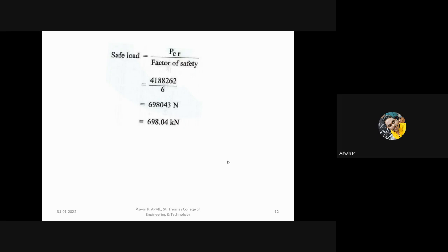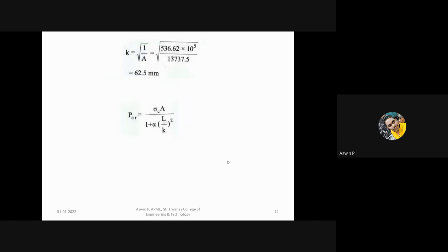So this is the method of solving a problem. We will once again check the problem and how we have done it. The given problem is a hollow cylindrical cast iron column, 200 outer diameter, 150 inside diameter. Please be careful. If you missed anything, you can learn now. We have time. It is 4 meter long, and both ends are fixed. To do different problems, you can change the values. Outer diameter can be varied, inside diameter can be varied, and the length of the column can be varied, and the end condition, both ends fixed, is given here.